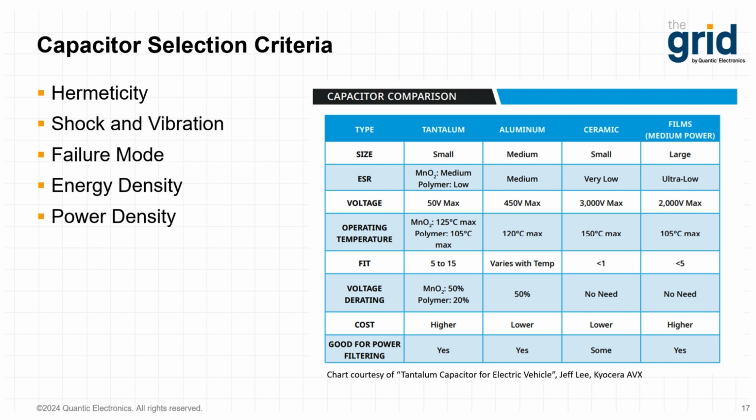Since the pressure is significantly lower at high altitudes or even non-existent in space, non-hermetic capacitors can leak electrolyte, introducing a variety of reliability and safety issues. When designing a piece of equipment for these types of environments, and when specifying a capacitor for these types of environments, hermetic capacitors are often a common requirement.